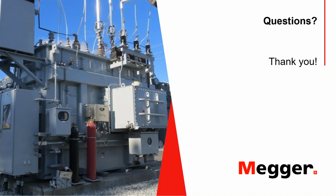That's by doing demagnetization. Now, if you review industry standards, the key aspect they mention is that the magnitude of the current you use to demagnetize the core should be the same as what you used to measure the winding resistance in the first place. So if you used 10 amps to measure the resistance of a transformer winding, in order to demagnetize, you should use that same magnitude.